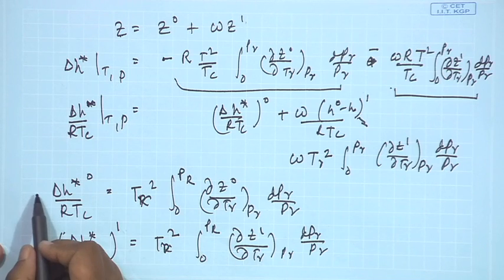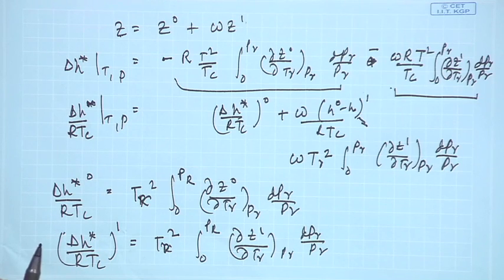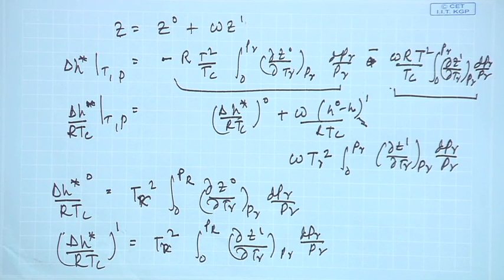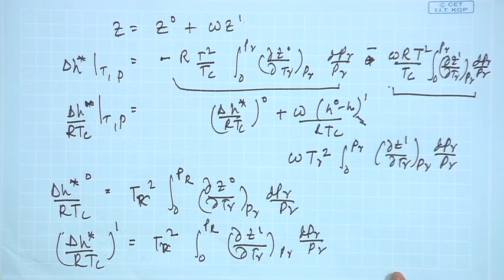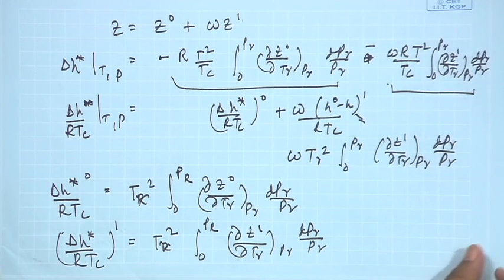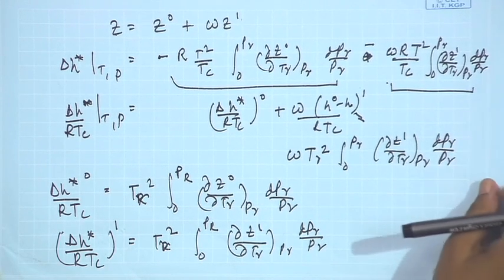So therefore, just like we had discussed for the case of the compressibility factor, in this case also we find that for greater accuracy we need to incorporate not only the 2 parameter but also the 3 parameter law of corresponding states. A similar exercise can also be performed for the entropy correction or the entropy departure function as well.